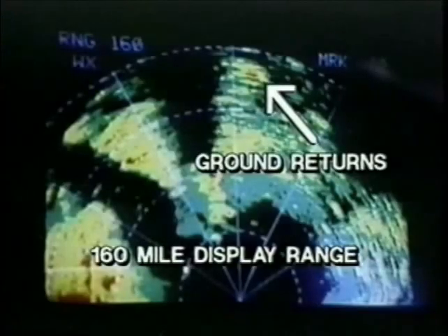If during the flight a radar system is suspected of having poor range performance, a confidence test should be initiated. A radar system that is functioning correctly should display ground returns out to a distance of at least 160 nautical miles. To perform this test, the aircraft needs to be at an altitude of at least 21,000 feet AGL. If the radar will display ground returns at that distance, it will display weather correctly.